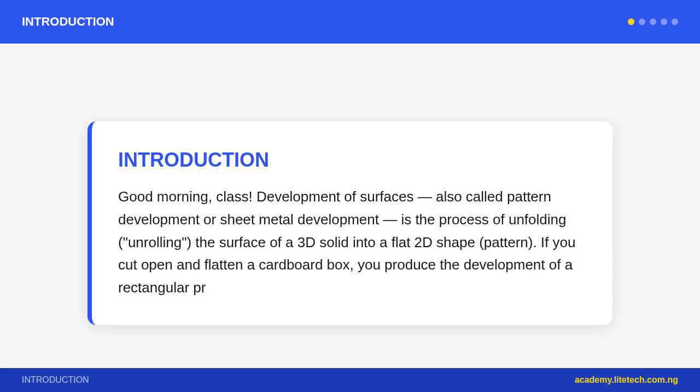Development of a rectangular prism, a box. A box with dimensions L times W times H, length times width times height. Step 1. The development consists of 4 side faces plus top base plus bottom base. Step 2. Lay the 4 side faces flat in sequence.